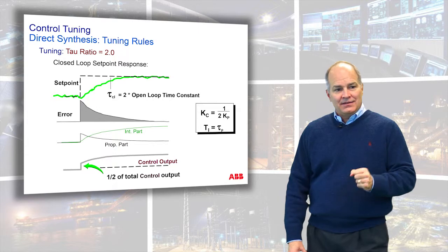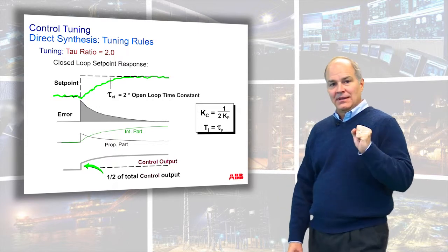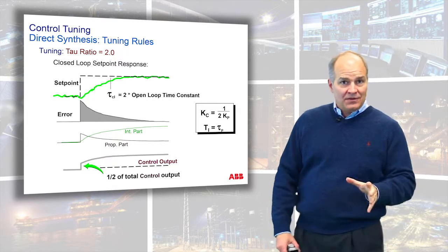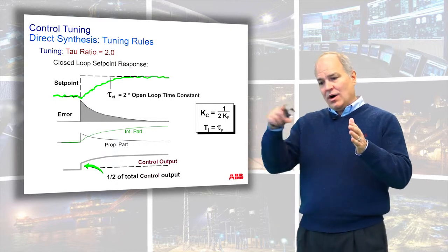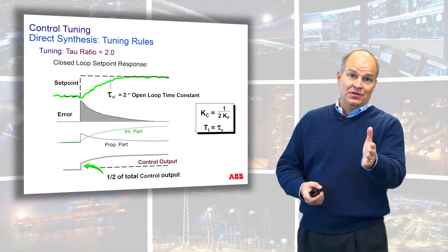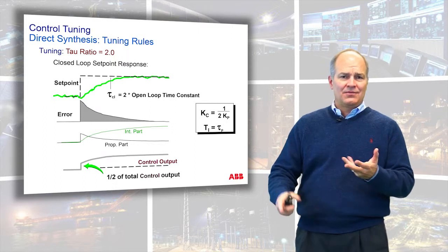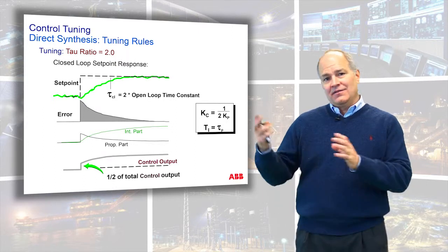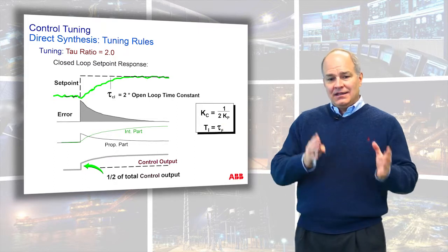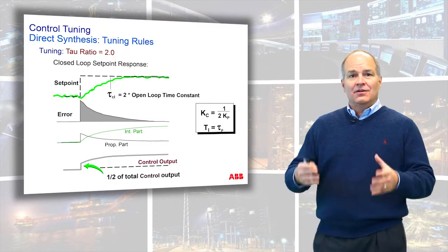Most people ignore that. They do their bump test, they come up with their tuning, and they plug it in and walk away. Don't do that. Change the set point and watch your control work. It should do what you told it to do, and if it doesn't, you missed something. You got the time constant wrong, the gain wrong, there's a nonlinearity, the valve's in a different position. It needs to match.